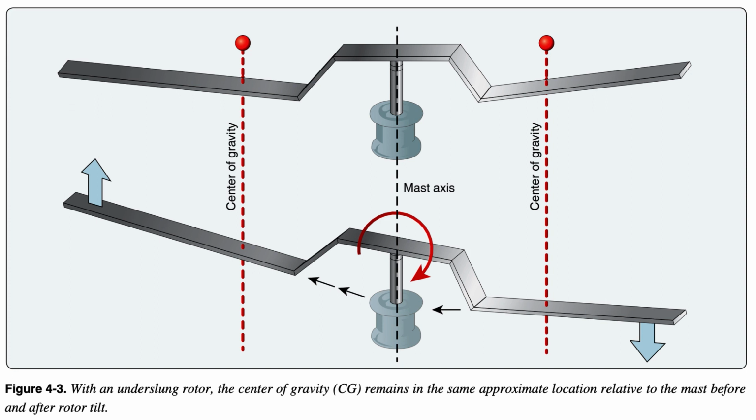Flapping angles increase slightly with high forward speeds, at low rotor RPM, at high density altitudes, at high gross weights, and when encountering turbulence. Maneuvering the aircraft in a sideslip or during low-speed flight at extreme CG positions can induce larger flapping angles.